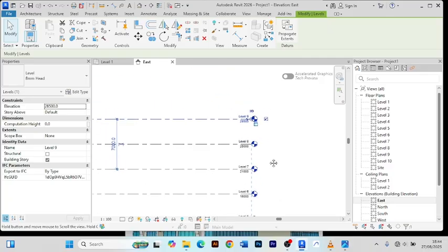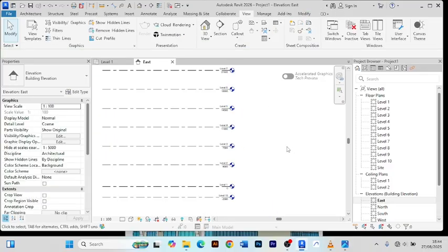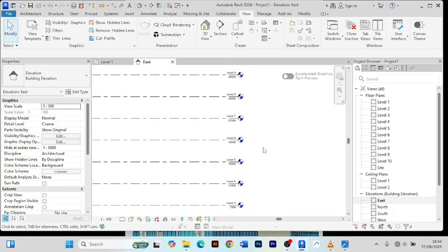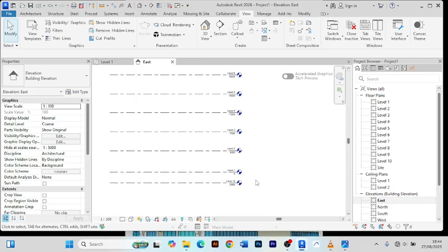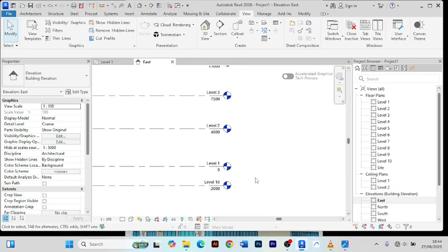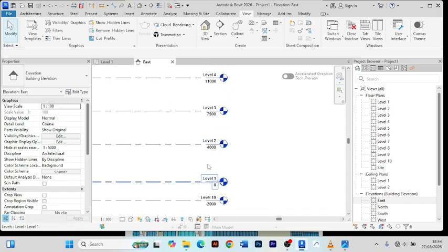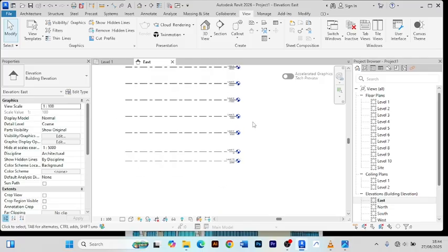And then I guess that should be it. That should be the end of our levels. So for now, it really doesn't matter how your levels are, but all you need to do is give the floor to floor height according to what you feel your design needs. For example, the ground level to the first level, I gave it 4 meters, and then from here up, the rest have been given 3.5, 3.5. You can also do more than 3.5, you can do more than 4. So it's not static to these things that we have shown.